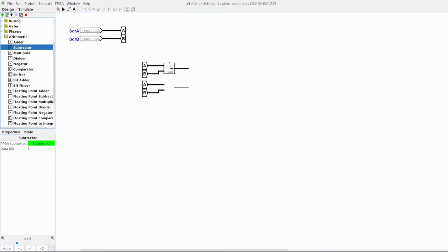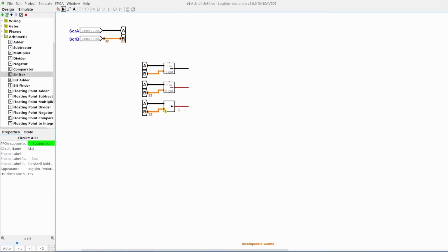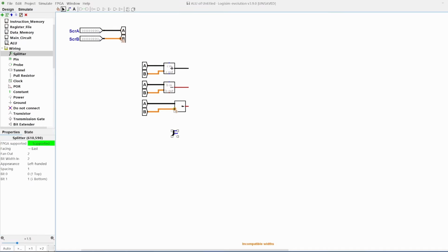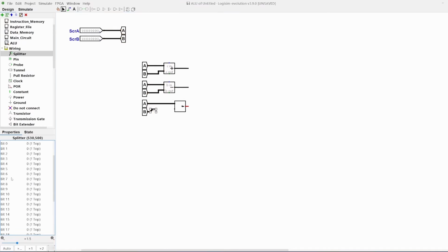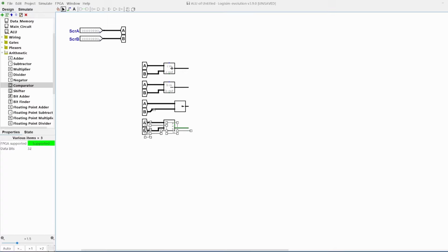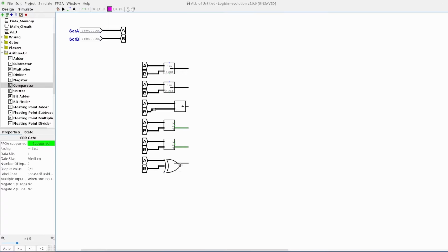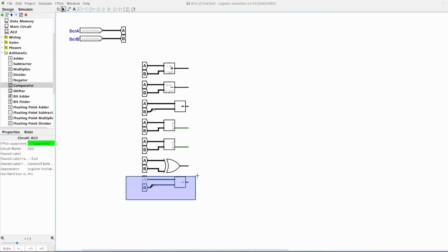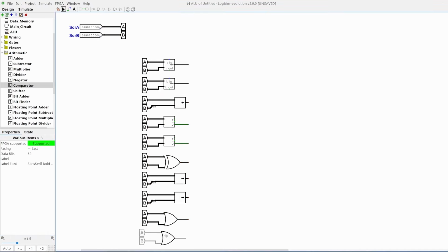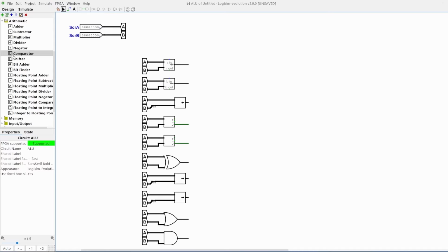I'll not worry too much about making this an efficient simulation, because this is just for educational purposes. For the shifters, also throw away the last 27 bits of B and only keep the first 5, because the shifter just takes in 5 bits for the second input. Now we have 10 outputs, which you need to choose one output from. This can of course be done by a mux as before.